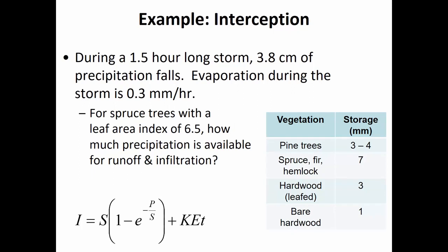Because there's always going to be some precipitation that maybe it's a leaf that's not flat. That's what this is trying to account for. It's not like the tree gets fully saturated and then it starts pouring at the same exact rate. Even when you're standing under a tree during a rainstorm, you'll definitely stay drier, but it's not like none of the raindrops get through there at the beginning. They gradually increase the amount that can penetrate down through the canopy. But the sum of these two components, the interception is going to be 9.89 millimeters.